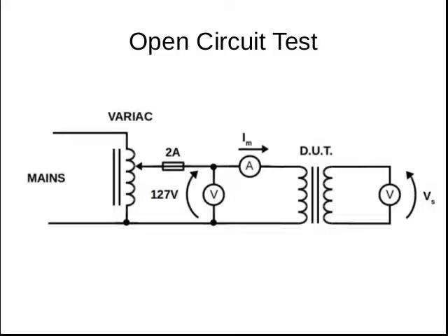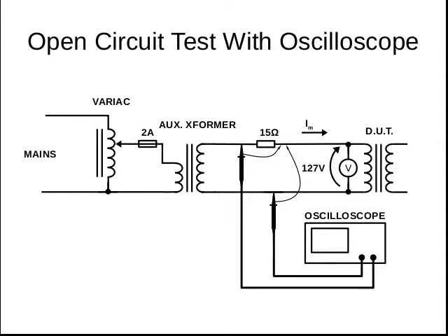Connecting the oscilloscope like that, we can measure the voltage on the 15 ohm resistor, which will be the magnetization current multiplied by its resistance, on one channel and the voltage on the primary on the second channel. Obviously we will have to invert the signal on the second channel because the ground of the oscilloscope, which is also its reference, is connected against the conventional polarity for voltage.